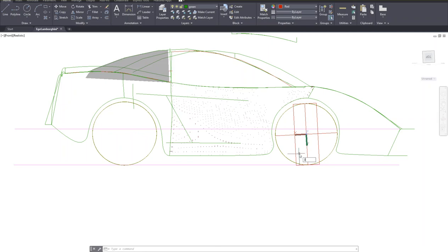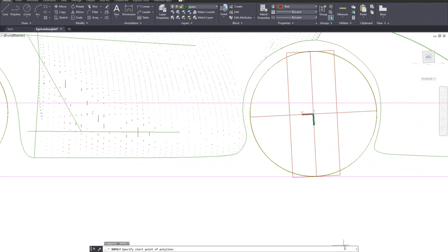I need 3D poly. I always use the 3D polyline. I set the grid snap to 1 inch, but it is jumping all over the place for some reason. Maybe I should double check what's going on. Grid snap, snap settings. Let's go down to the 1 inch setting.